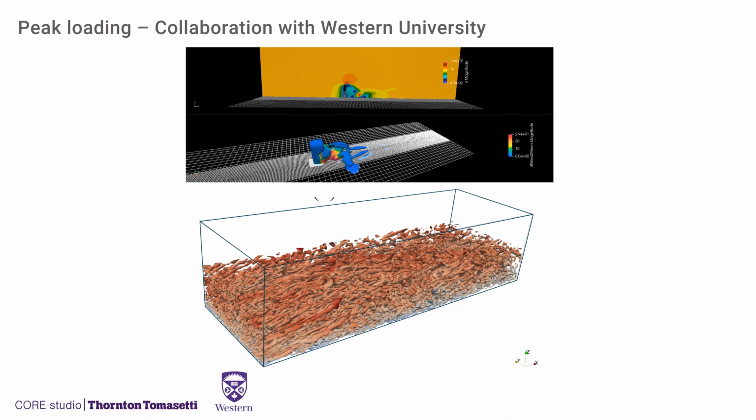So it's really the mean velocity that is important for pedestrian wind comfort, but the gustiness creates dynamic peak positive and negative pressures. And to simulate that correctly in the CFD, in the digital simulations, is key. That's embedded within the physical wind tunnel test, but it's not that obvious for CFD. So we started to work together with Western University in London, Ontario, Canada, with Professor Bitsuamlak.